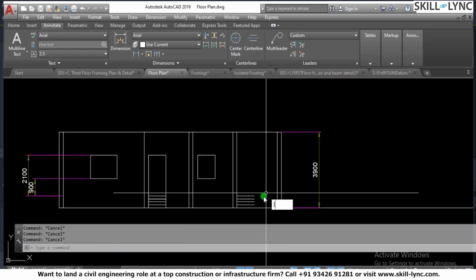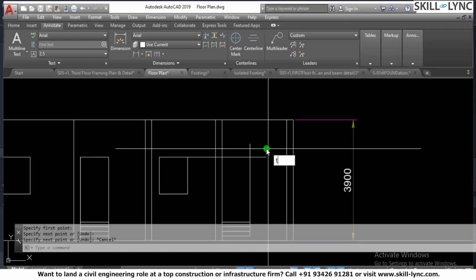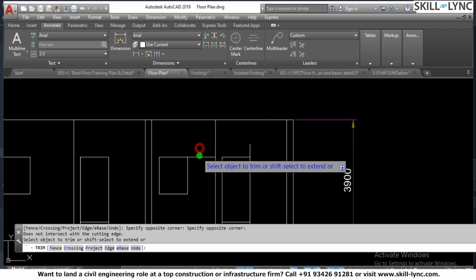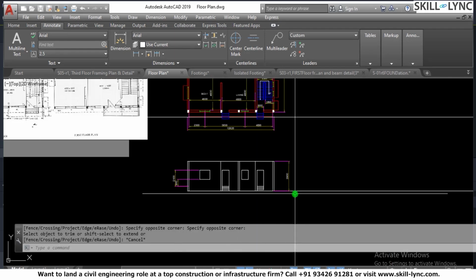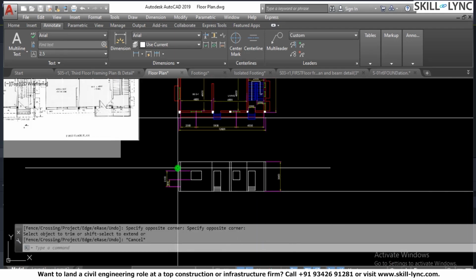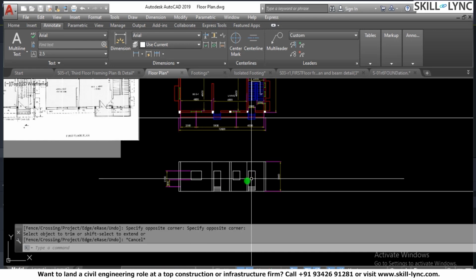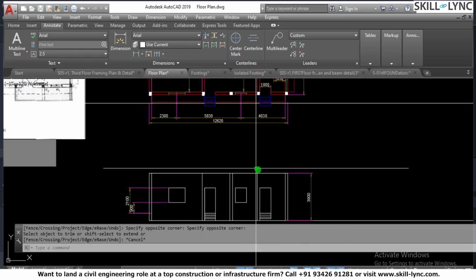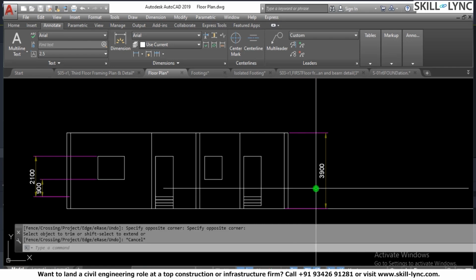So here you can draft, and you can always draft the windows and the doors as per the requirement. What we did right now: there is a column at the end, a column at the start, and there is one window opening, 2 door openings, and another window. This is the height from the top of the plinth beam. Let's say I can write TOB from the NGL.